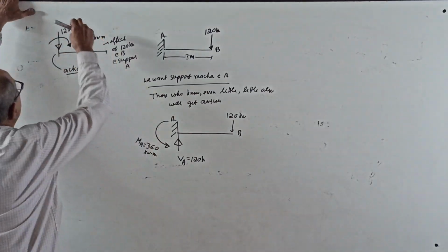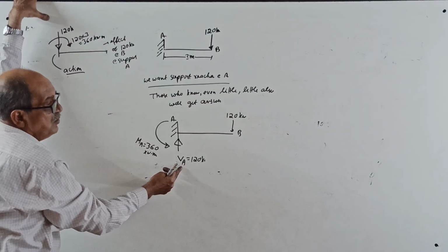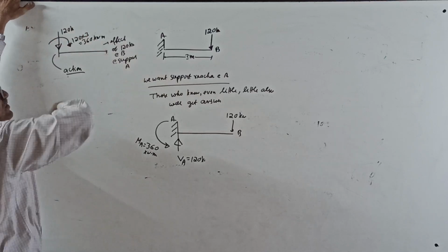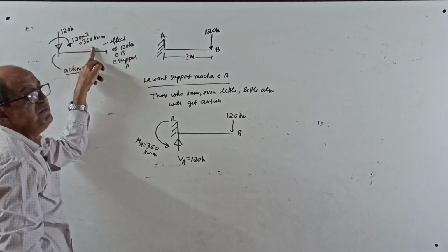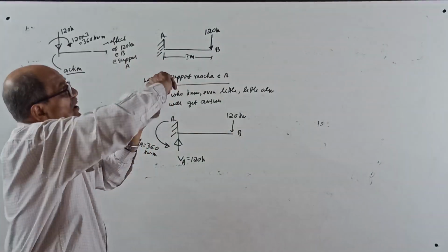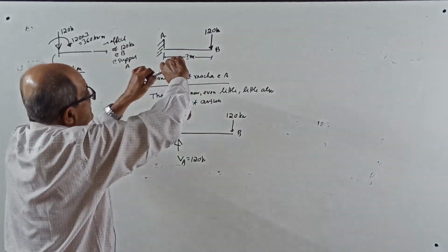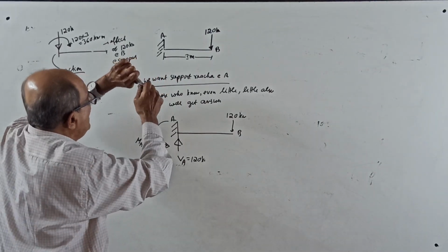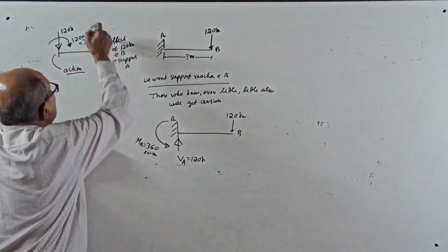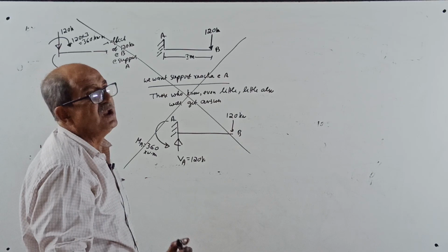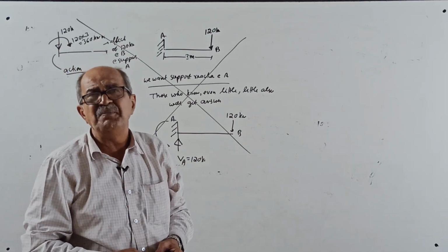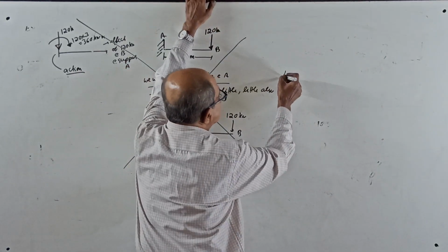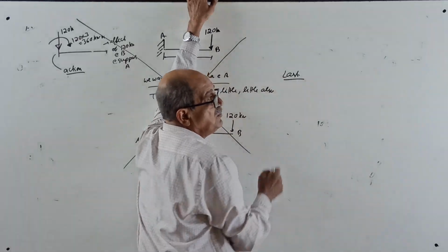That is why when it is pushed down by 120, the support gives an upward reaction of 120 for equilibrium, and when the load tries to rotate the support by 360 clockwise, the support gives a reaction of 360 anti-clockwise for equilibrium. If not clear, leave it. Don't worry. I told you now, that's all. But 99% of people understand.